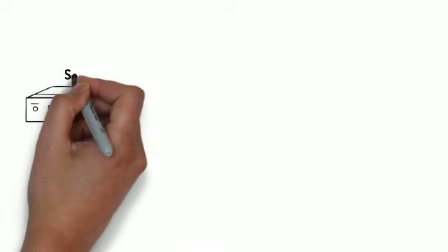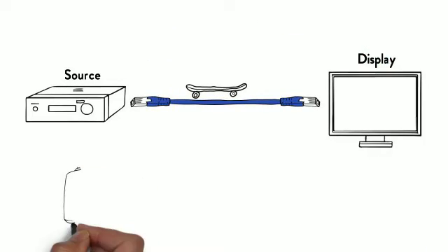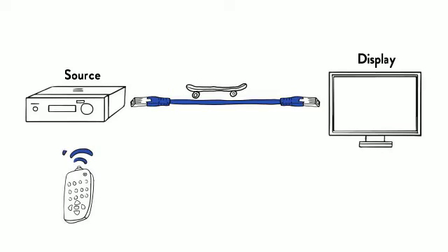IR is transmitted both over the air and over an HDBT channel. Over the air, the signal is transmitted from the light emitter to light receiver. Over HDBT, the signal is transmitted from the IR receiver to the IR transmitter. HDBT extends the range after receiving the signal.